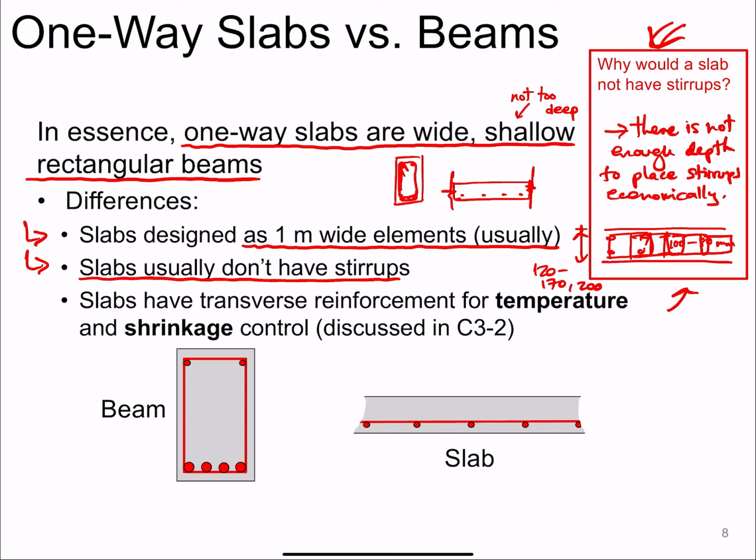We have other sorts of steel hardware that we can use when the slab is really big, but usually we are going to rely on the concrete contribution alone to carry shear. So we are not going to be depending on stirrups or any other steel reinforcement in most slabs to carry shear forces. Now, when we have very high shear forces near the supports, sometimes we use a different type of reinforcement, but it's not going to be the focus at this point.